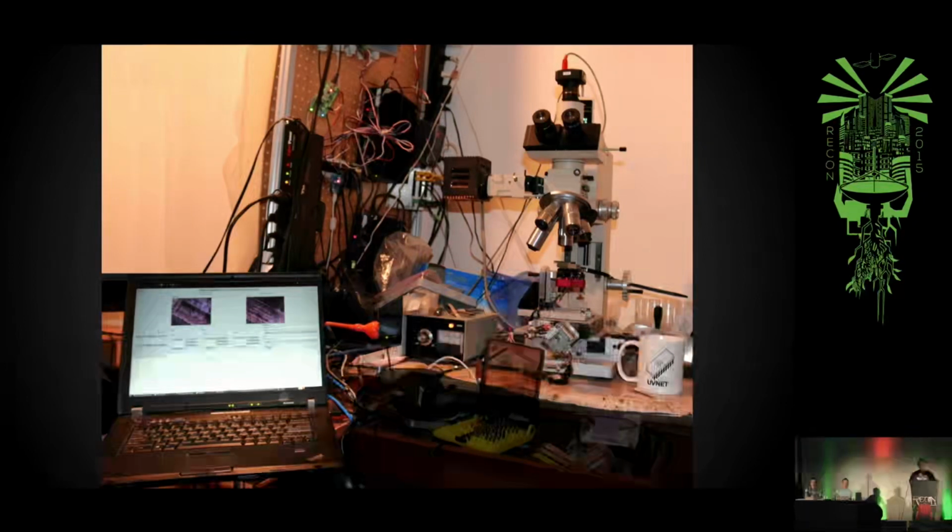Everything's hobbled together, and somehow it managed to make a working system. Basically, the way that it works is there's a lamp house which shines light onto the die. The objectives actually do the magnification. And then the motors go through an ARM processor that I wrote some very crude but effective C code for. That goes over a USB serial interface to the laptop in the lower left corner. That runs some Python as well as a camera driver I wrote for the microscope camera. And that's able to take pictures from the USB camera and then send commands to the ARM processor to issue step commands to move the stage one bit at a time. And that's how I produce the images that are later used for analysis.